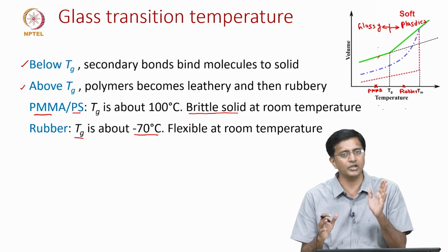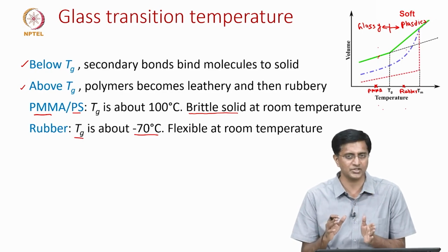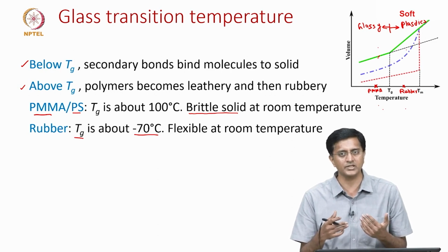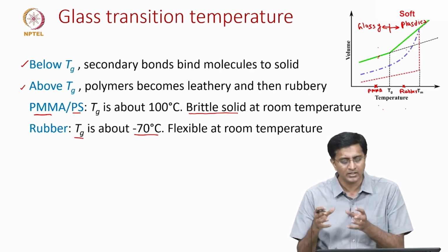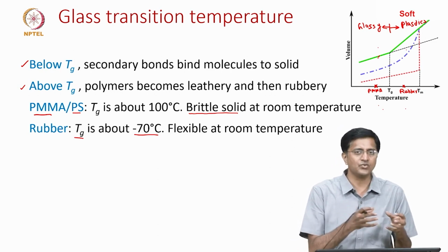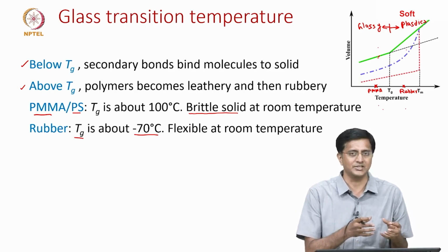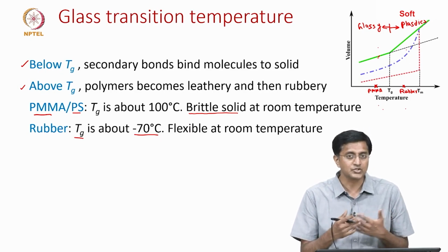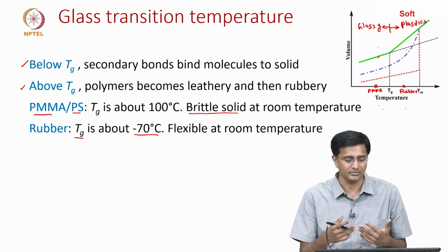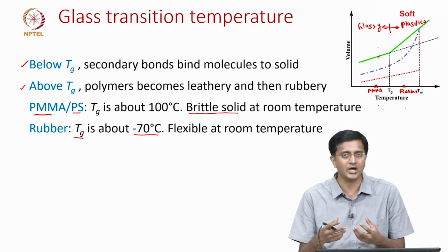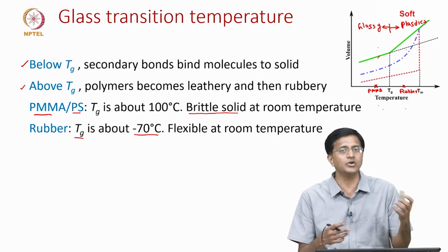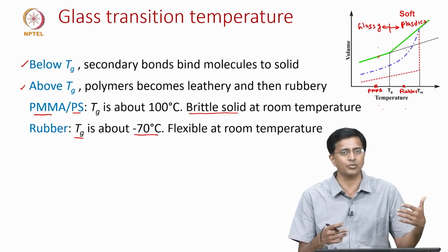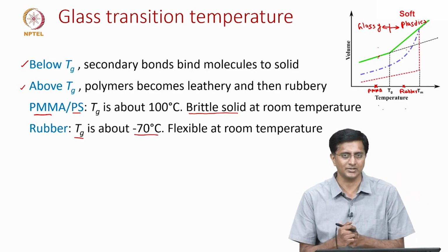But if we go even further below the glass transition temperature, which means around minus 100 or minus 120 degrees centigrade, that is when the rubber has transformed into the glassy state, where it now shows solid behavior, or becomes hard. The same rubber shows hard behavior when it is below the glass transition, which happens at temperatures in the order of minus 100 or minus 120 degrees centigrade.